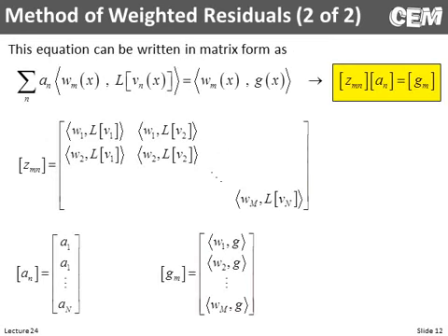It turns out this can be written in matrix form. This is completely numerical now. And we'll have a big matrix Z, which really comes from these inner products, operating on this column vector of unknowns, which are our weights now. And so once we know these, then we can multiply those by our basis functions, which we also know, and reconstruct our unknown. But we have this big matrix Z operating on our unknown coefficients, which were the weights on our original expansion functions, equal to a column vector, which is really a comparison of all of these different basis functions to the excitation.